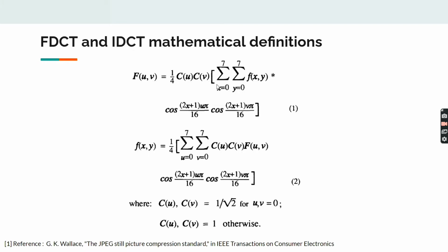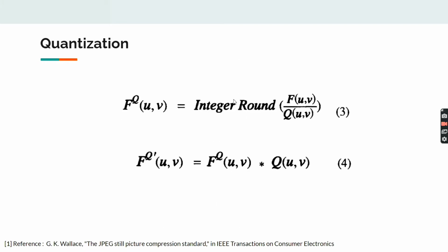Mathematics of quantization. Each DCT coefficient is divided by its matching quantizer step size and then rounded to the nearest integer. The quantizer step size is used to normalize the output value. Dequantization. Dequantization is the inverse function, which in this case simply means removing the normalization by multiplying by the step size, which returns the output to a representation suitable for the IDCT.